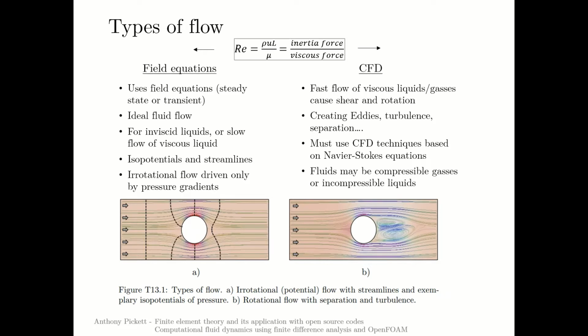You could replace the temperature boundary conditions with pressure, and you could replace the conductivity with permeability, and then you would use exactly the same algorithms, exactly the same modeling and analysis techniques to do the prediction of fluid flow. The results are shown on this diagram at the bottom here.